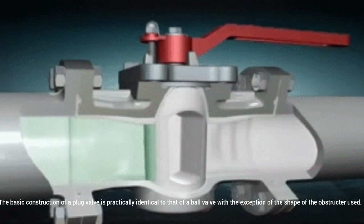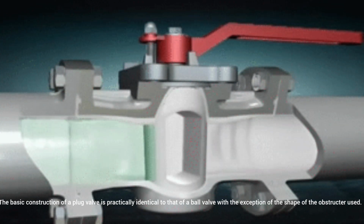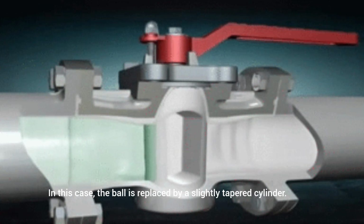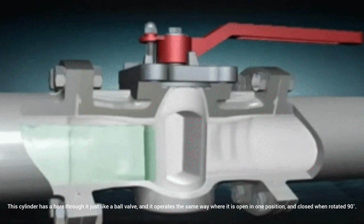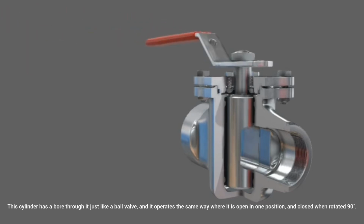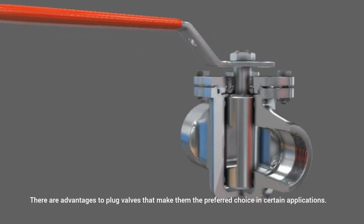Next, plug valves. The basic construction of a plug valve is practically identical to that of a ball valve, with the exception of the shape of the obstructor used. In this case, the ball is replaced by a slightly tapered cylinder. This cylinder has a bore through it just like a ball valve, and it operates the same way, where it is open in one position and closed when rotated 90 degrees.